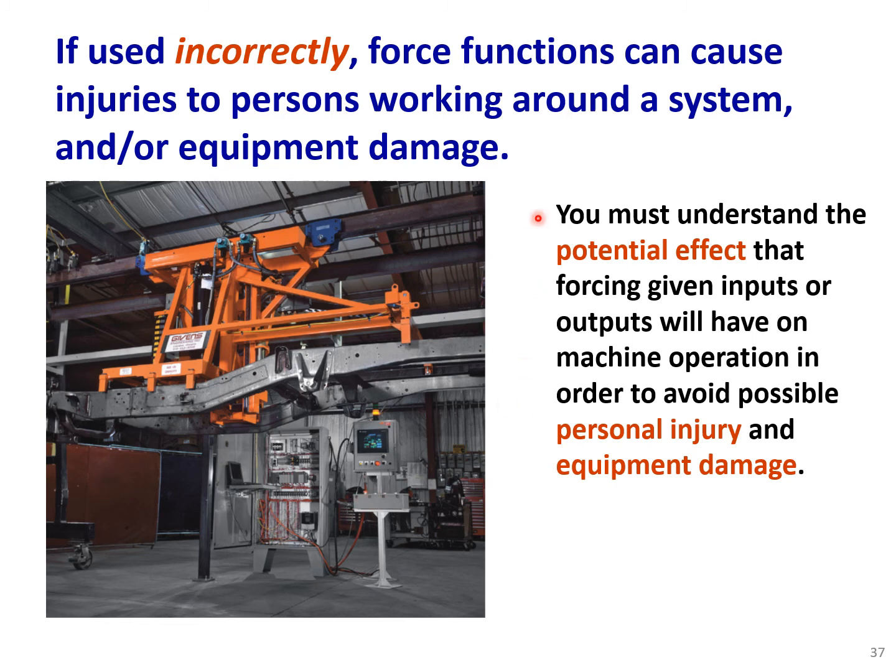You must understand the potential effect that forcing an input or output will have on machine operation in order to avoid possible personal injury and equipment damage. So we should be very careful when we do the forcing, specifically for complicated programs.